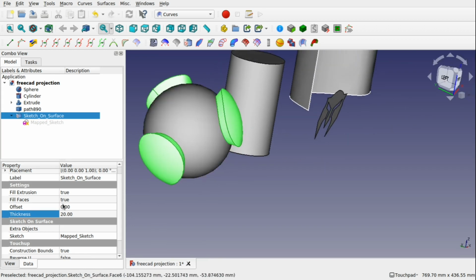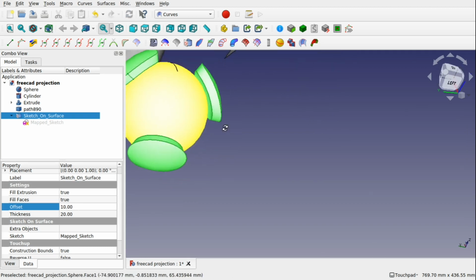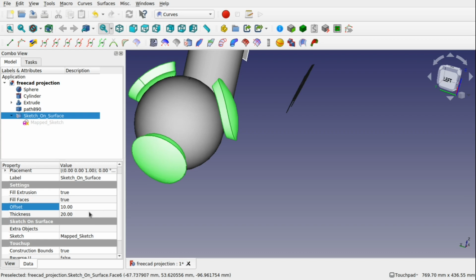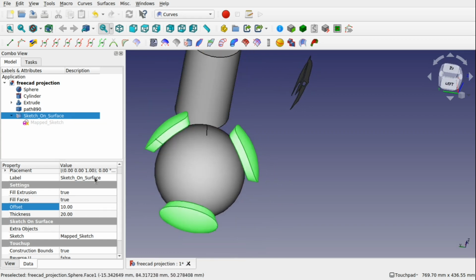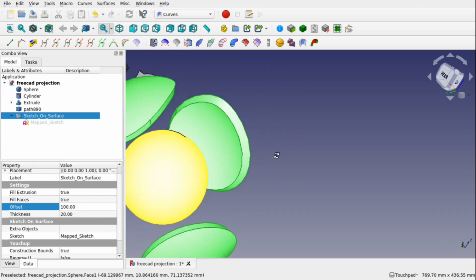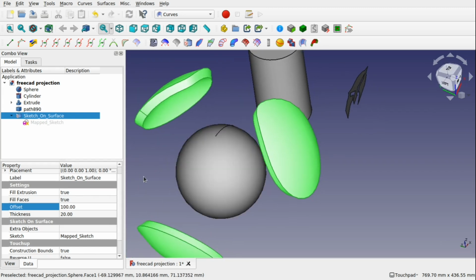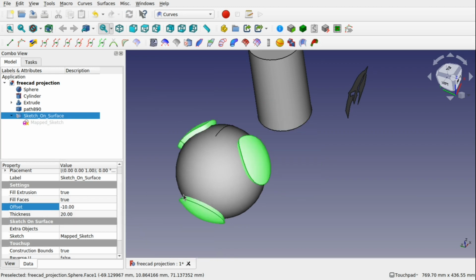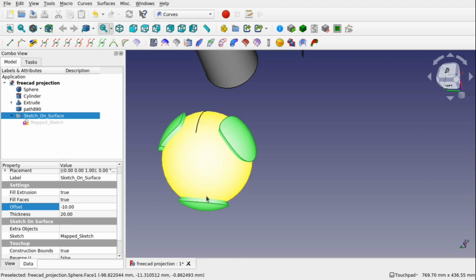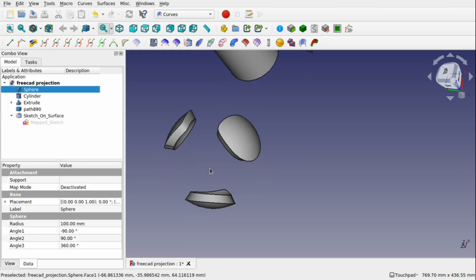We can use an offset to pull these in. So if I put 10 on here, that will push those out. Sorry, let's push them out. Positive pushes them out. So I did 100. Let's push them right out here. And if I did -10, then that will inset them in. So -10 on there. So we've inset them in because they're 20 thickness and they've gone 10 in. So if I hide that, you can see those are in there.